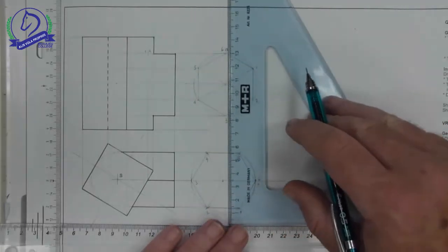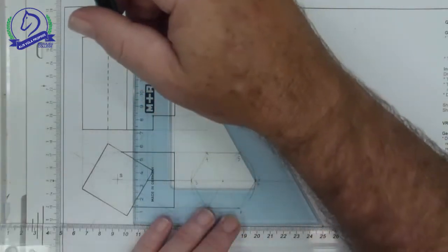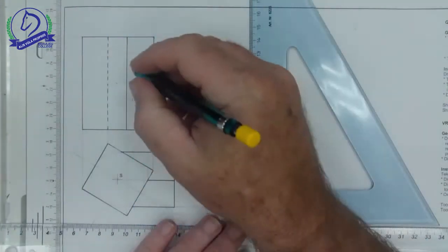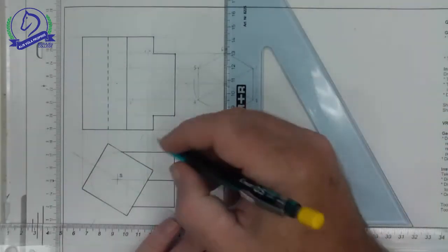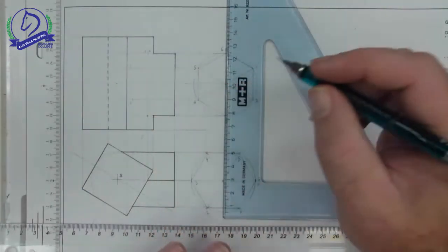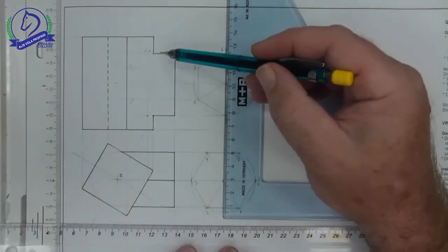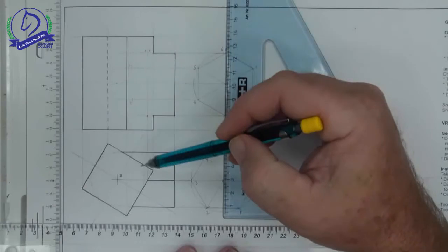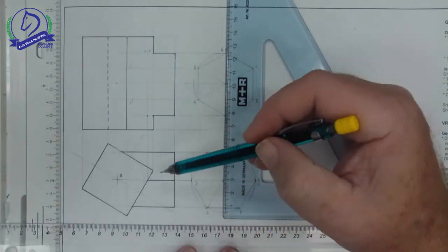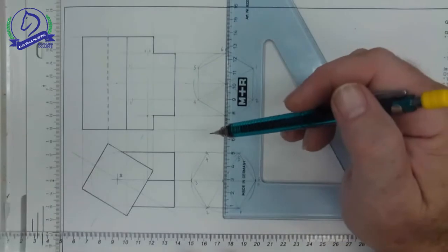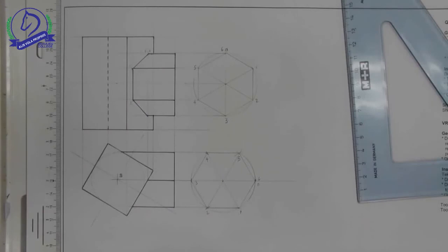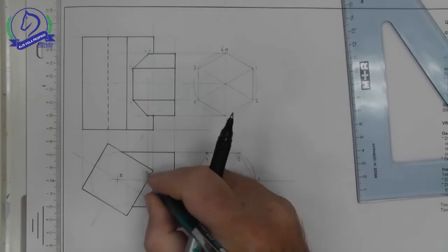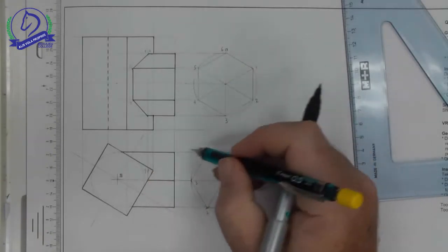Next is point 2, and I need to project that to point 2. Then point 3. There's point 3, and that's where it intersects. Now I'm going to stop there. Why? Because that is what is in front of the turning point and would be the visible part, and I'm now going to go over that in my outline. There is the completed visible shape. Now we're going to work around to find the turning point and our last points 4 and 5.